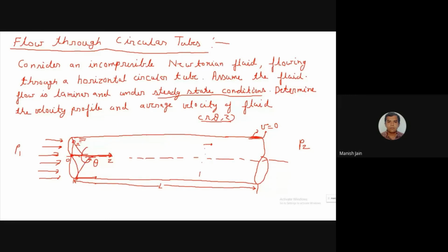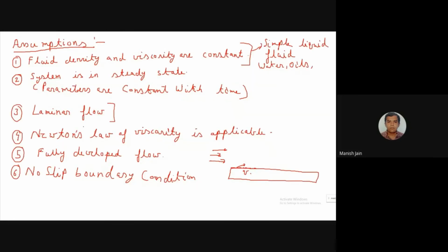Okay, so here the velocity is developing, and due to the drag, velocity is developing, and after some time, this is called the area or the region where the solid body has the effect on the flowing fluid. That is called the boundary layer, and where the thickness of the boundary layer is increasing, that is called the developing boundary layer. So what will happen?